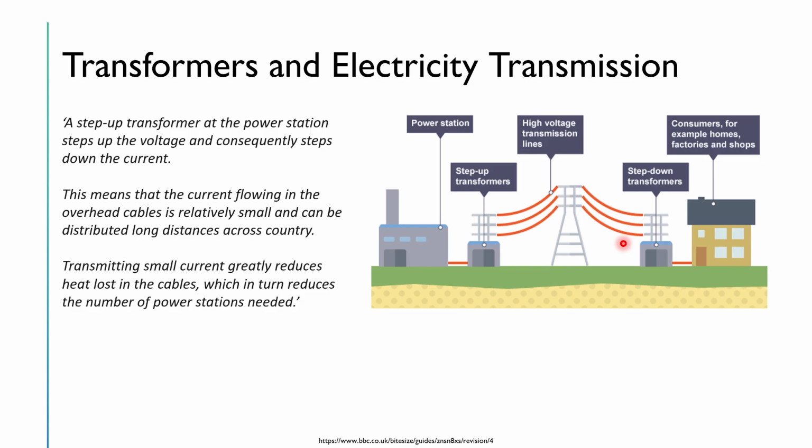What becomes a concern is as we bring some of these electrical lines closer and closer to people in residential areas and the like, we start encountering issues of safety. We don't want people to be in close contact with power lines of extremely high voltage, which can cause injury or death. And through this series of transformers, we step our electrical energy down and down until we get to our home grade voltage. For Australia, this is 230 volts.